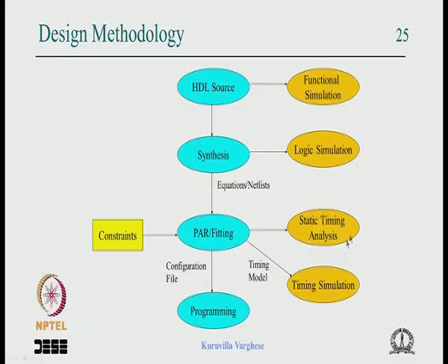And as a designer, you might find that 6 of them are violating the timing constraints you have put. But none of them may be used in the real-life circuit, so you can be misled in this game. So it's very important that when one does the static timing analysis, such information is given to the tool, saying what the valid paths are.